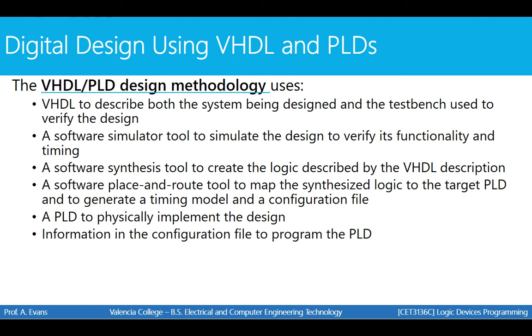And then the design methodology also uses information in the configuration file. That configuration file is generated by Quartus when we compile everything. And that's what's going to be used to physically program the PLD. And you're going to see all of these steps through this lecture to write the code and to get the configuration file needed to actually program the PLD.